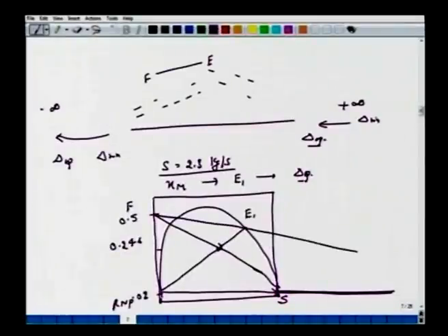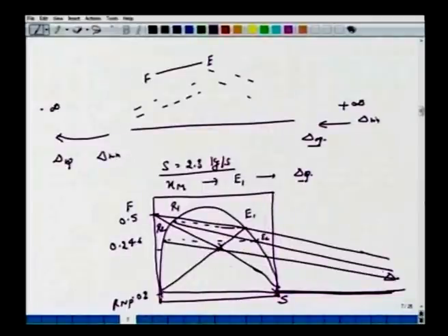So now if you extend the difference points, you get your operating del, then start making the tie lines, say E1. Here the tie lines were downward, so you get R1. First connect with this del. Again you have E2. You find the tie lines slightly start becoming flatter. R2, connect to this. You have E3. And at E3, you will see the tie lines have become exactly like this, and this will go below RNP. So we have stage 1, stage 2, stage 3.